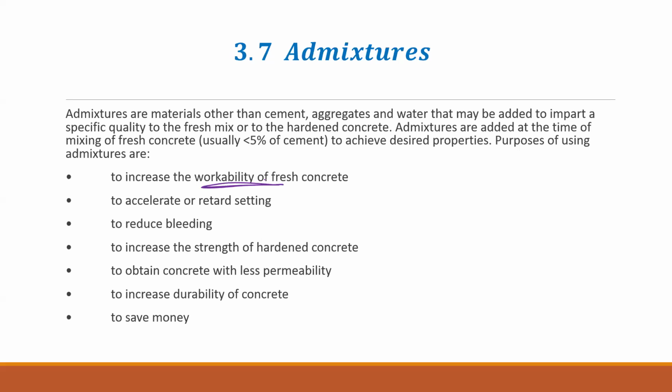So we can add these admixtures, plasticizers and superplasticizers. They act as a lubricant, like when you add a little bit of oil to bread dough, it is easier to mix. Likewise, plasticizers and superplasticizers act as a lubricant and improve the workability of fresh concrete.